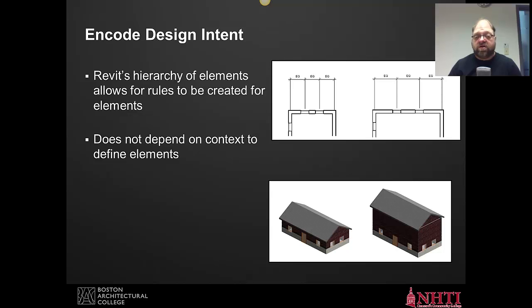I wanted equality constraints. So I can place a constraint, or I can build a relationship within my project, and then when I change those outside wall dimensions to make them wider to one another, not only is the L connection maintained, but the equality constraint that I built, that was my intent, I want those always to be equal, that's maintained as well. So this idea of design intent helps you make sure that all the objects within your design maintain the relationship to each other. And Revit builds some of the background by itself, but you can also build these relationships on your own.